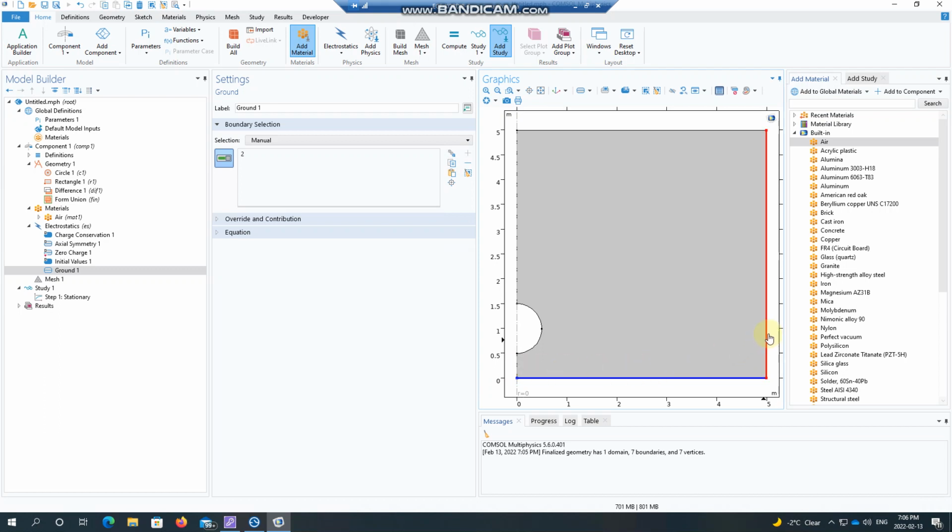And we select this box as boundary. So this should be also ground because this is our boundary. We need it if we want to solve electrostatic. Then we also need to consider 1 kilovolt on the sphere.